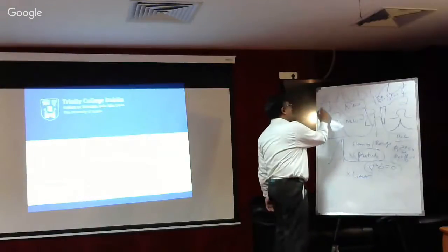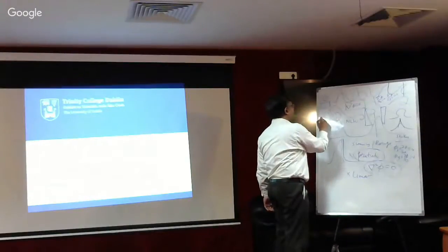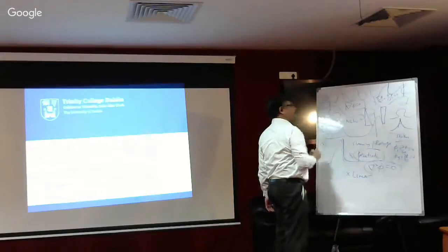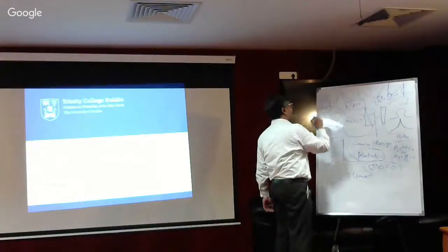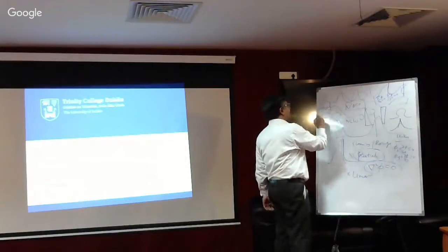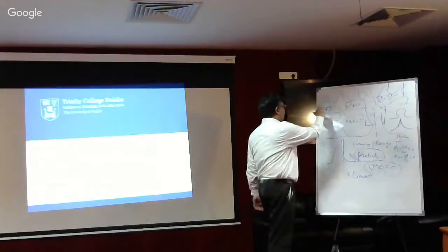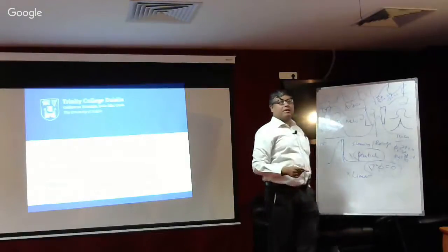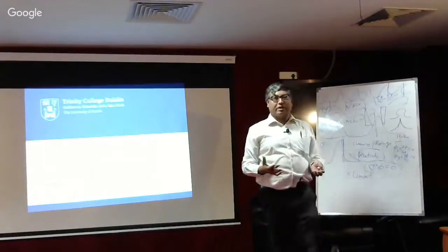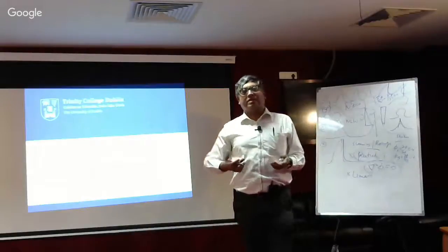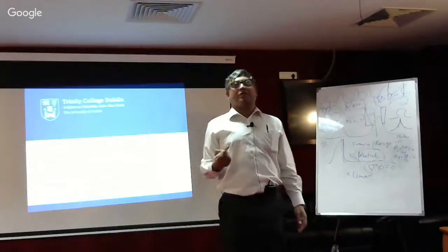So essentially, you have a flow like this. This is the bed, the ocean bed or river bed, and your wave is propagating like this. But below this, you might have a shear flow like an underlying current. And this particular current interacts with the wave, and the wave-current interaction will change something called a nonlinear dispersion relation.